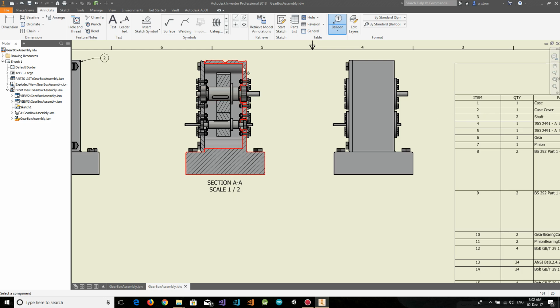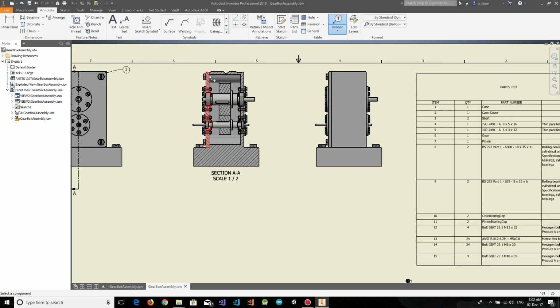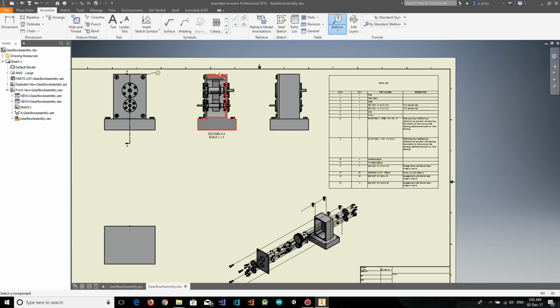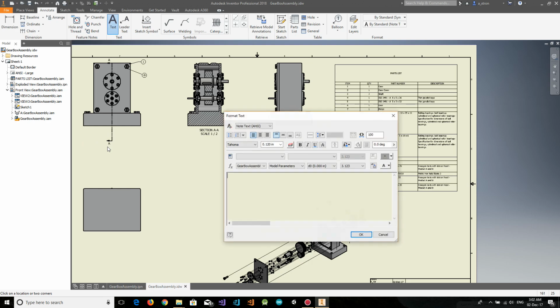There you can see that here we have some problem. It's like it's been eaten or cracked, so you'll have to go back and check into our design. But for now, this is what we have to do for our coursework. Scale this and move it a little bit up. So that's it. We'll have just to add the balloons for each part that you need to identify. This is number 15, which is this one, and the text for the front view and left view.